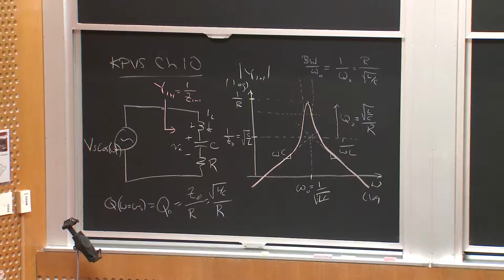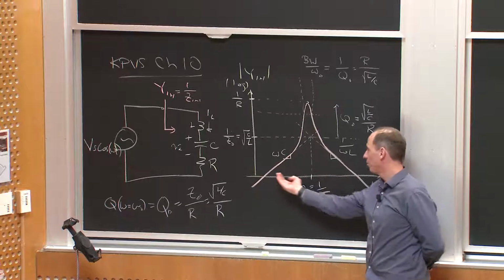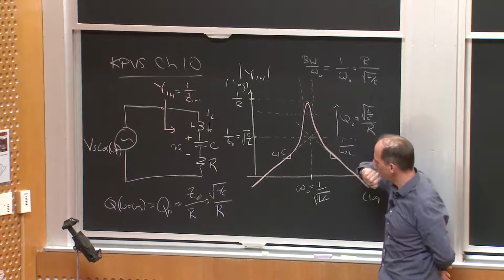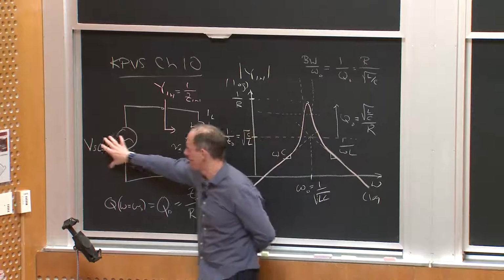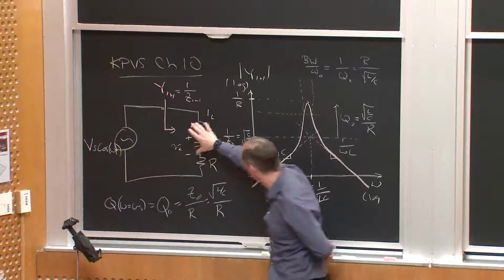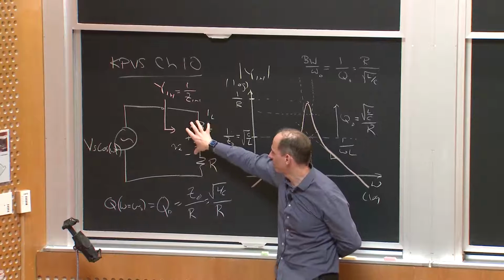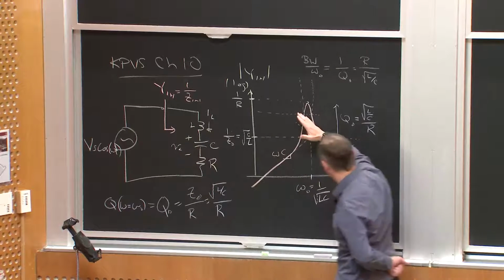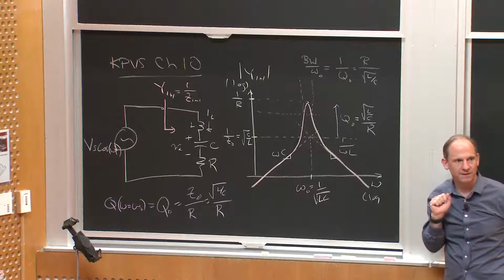Okay, so if we were to think about making an inverter, then by controlling frequency either above or below resonance, we can turn down the power, and when we're right at resonance, right, Vs appears across the resistor. So that's the maximum voltage I can generate in the resistor, because that's where the inductive and capacitive impedances are canceling. And at any other frequency, I'm going to have either a net effective inductive reactance or capacitive reactance in series, so I get a voltage divider, my admittance goes down, and I deliver less power. Okay? Any questions about that?